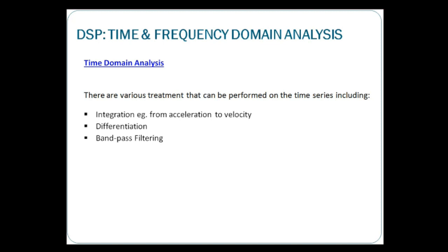Then we perform bandpass filters to filter out the signal that we do not want, in terms of its frequencies. We only focus on the band of frequency that we want to analyze. We can also do statistical operations, because it's the time domain and everything is raw. The overall RMS values can immediately tell us where the maximum value and the minimum value are.